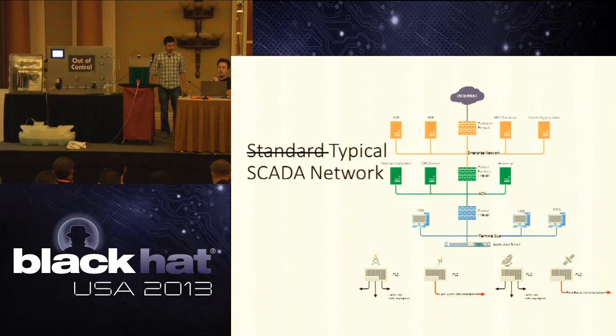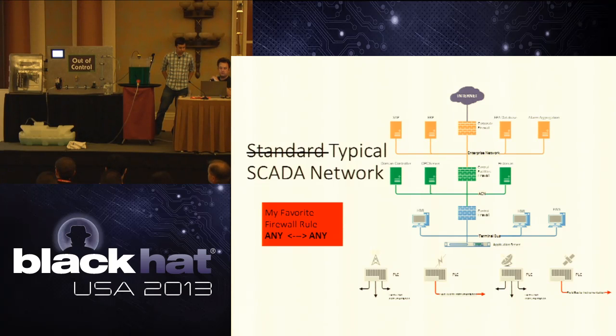There we go. Yeah, and this is a typical SCADA network. This is kind of the recommended network architecture where we have multiple firewalls in place to segregate the traffic types. However, if we move on to our next portion here, a lot of the firewalls that are implemented are really just put in place because somebody needs to comply to a standard, and they end up leaving their firewall just allowing all traffic to pass, which isn't really a firewall at all.